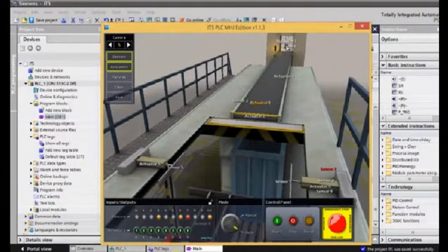So we are going to say if sensor M0.2 takes no boxes for a small period, let's say seven seconds, we are going to bring some boxes through a marker called M0.7.